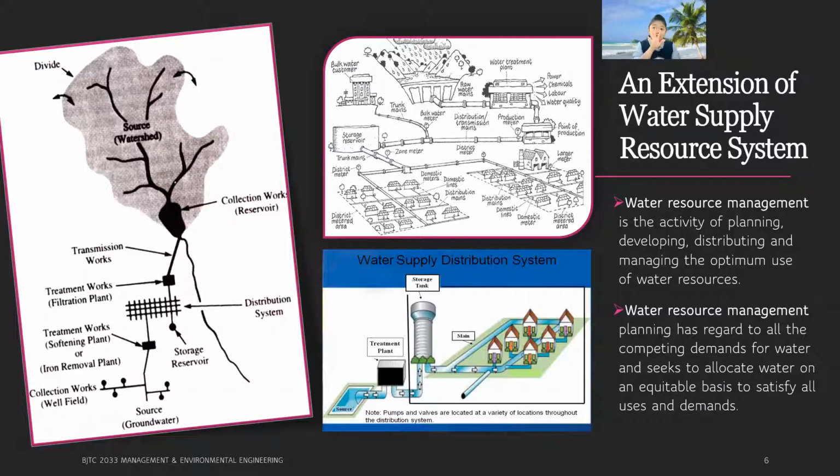So the house is actually five. Each of us will use 225 liters. This is what we are allowed when we're doing the design. One person, every day, in the planning, we are using 225 liters per person.